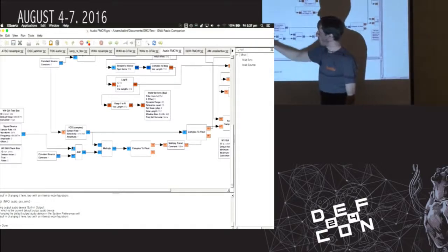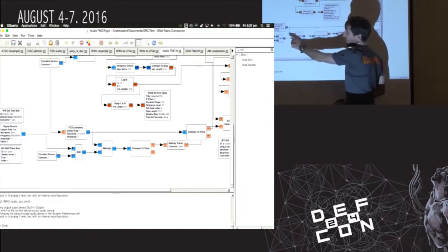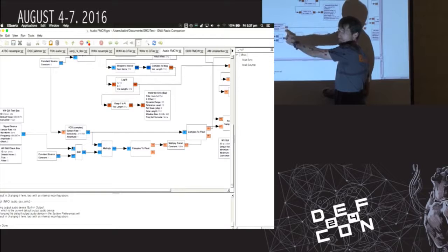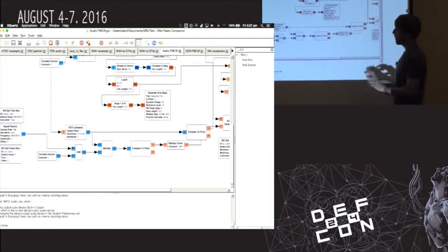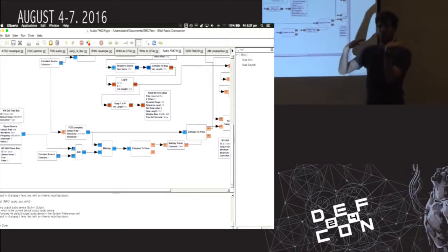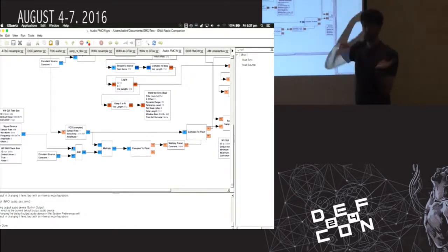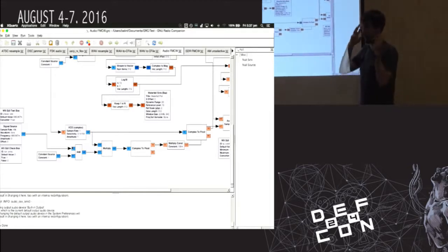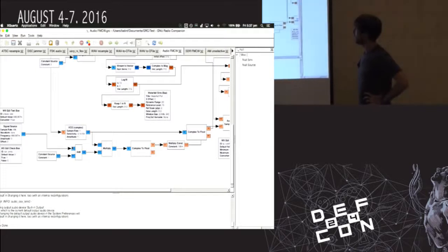And although this is a slow sine wave, this has the effect of changing the phase slowly of our chirp signal. And once you then take the real component and put it out the right speaker, we've got 2 chirp signals that are offset in phase. One is a constant phase, and the other one is retarded in phase and then forward in phase as they come out the left and right speakers. And that's why you get that weird stereo effect, because obviously you can hear it on either side of your head. And that's all there is to it.